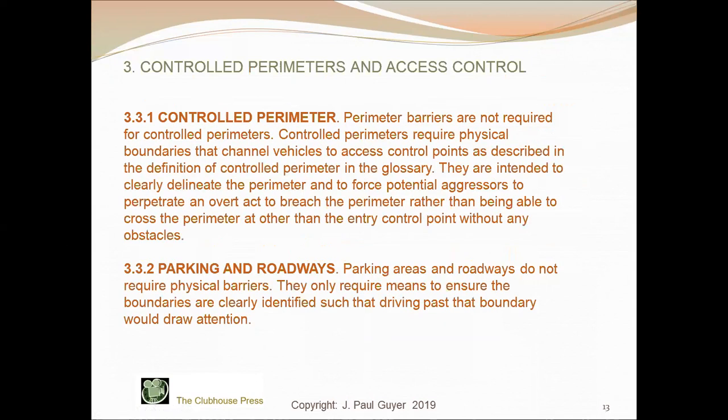So the controlled perimeters that are described in this discussion, and you will see the sketches of the recommended controlled perimeters further on in this discussion. Perimeter barriers are not required for controlled perimeters. In other words, it's not mandatory that you have constructed walls or fences or things like that.